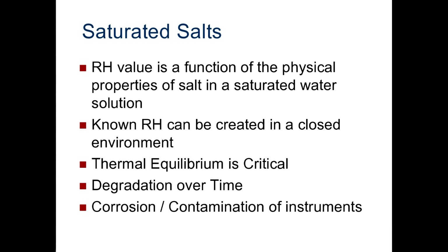And going back to that diagram, we can see that the saturated salt slurry, it's not hard to imagine that it has a very different thermal mass from the air above it. And if there's any small changes in the ambient temperature, the temperature of that salt slurry will be very slow to change compared to the air. The system will not be in thermal equilibrium, and the humidity fluctuations can be very extreme, many percent of RH from even a small temperature change.